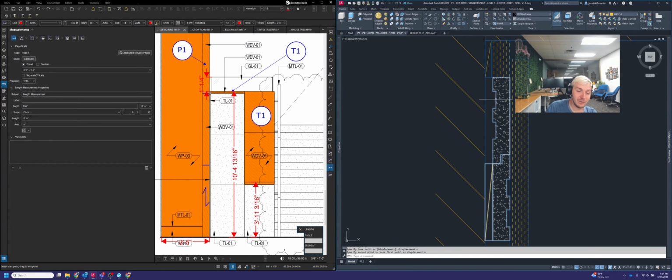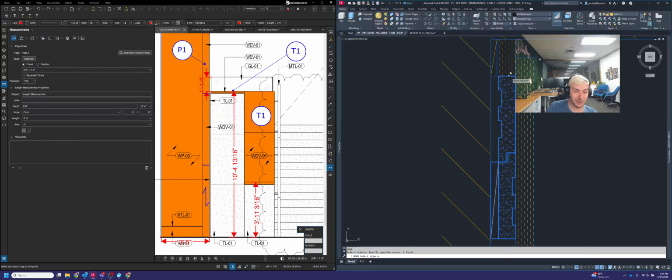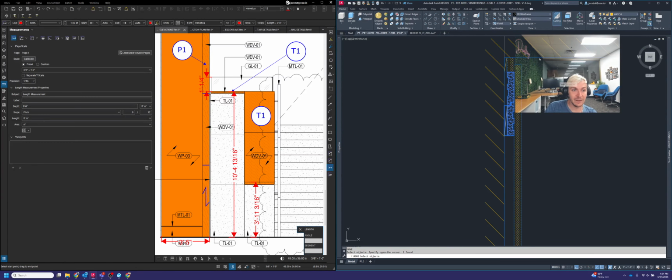And right now, what we would have done with that is we would have made a lock where you're not able to move this panel and cleat up because it's fixed together, and this block is right above that. So what we're going to do is we need to make sure that we at least have a 3/4 inch gap between that top cleat and the bottom of the reveal block. I'm just going to make it 1 inch tall.